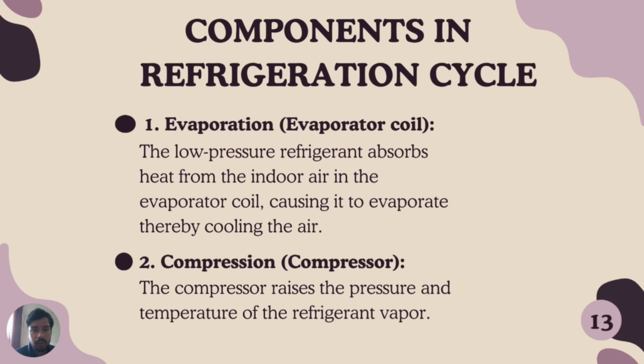Starting with the first component in the refrigeration cycle, the evaporator coil. The process undergoes evaporation, where the low pressure refrigerant absorbs heat from the indoor air in the evaporator coil, causing it to evaporate, thereby cooling the air. And then it enters the compressor, where it undergoes the compression process. The compressor raises the pressure and temperature of the refrigerant vapor.